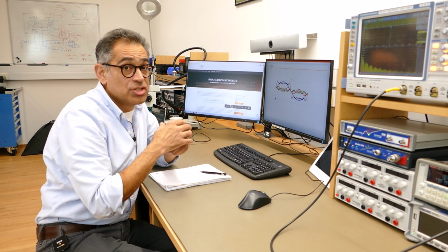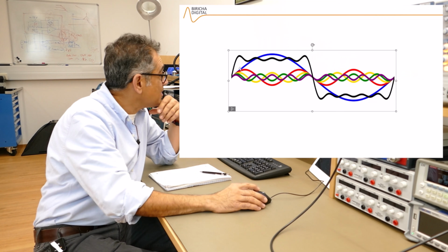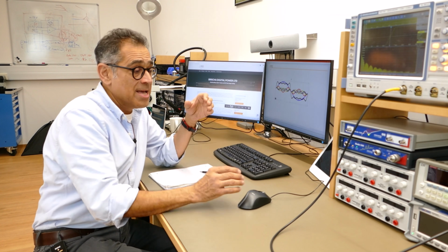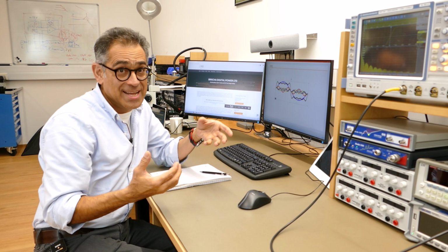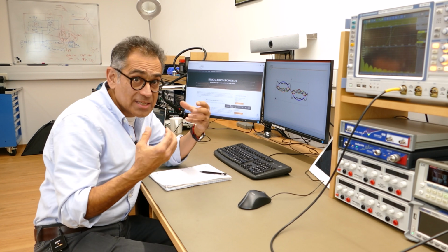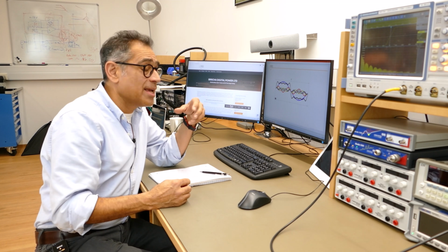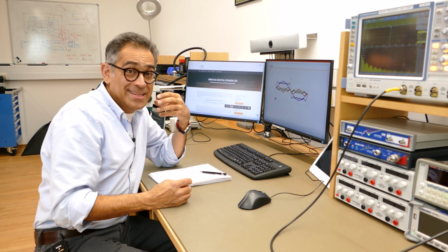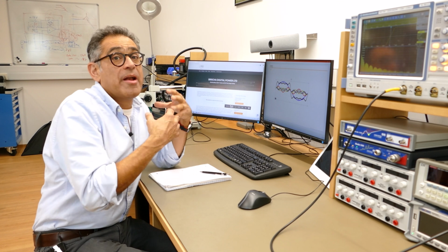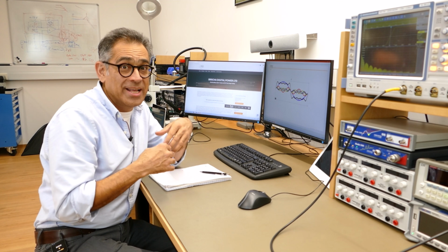It follows, therefore, that if you have got a current that is changing very fast, in other words, it's got very high dI/dt, and this edge here is extremely sharp, it has got very high harmonic content, and of course that high frequency is what couples with the parasitic inductances on the PCB. The same thing applies to a voltage waveform that has got a very sharp edge, and again that will have very high harmonic content, and that will capacitively couple just like we showed in the other videos.